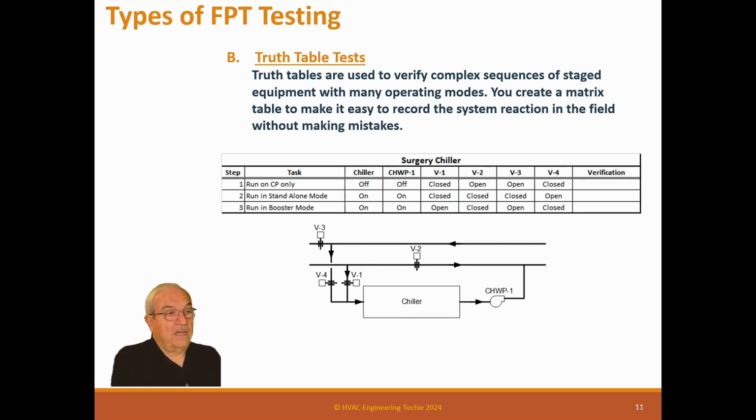During these times, we might bring a surgery chiller on because surgery still needs the really cold chilled water. Normally we bring on an air-cooled surgery chiller during the winter modes, when the outside air temperature lets this air-cooled chiller really make cold water for the surgery suite, and the rest of the hospital can have elevated chilled water temperature, which saves a lot of energy.